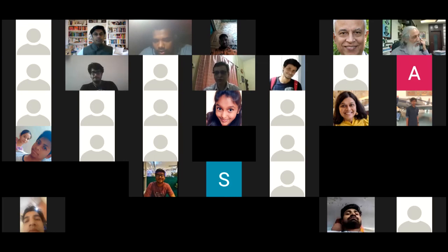I don't want to go into details. For example, when you test a chip, sometimes you don't even make a PCB. You just take the wafer from the foundry and do something called direct on-chip testing. For direct on-chip testing, the probes that you have in your lab should match what you are actually sending for layout. So this is another important feature.